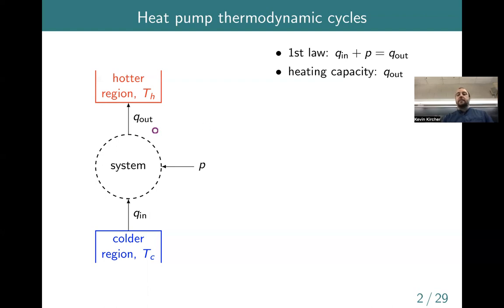Okay, we call Q out here the capacity of the heating system. So, if you're trying to figure out how big of a heat pump you need to keep a building cozy in the middle of winter, you'd figure out essentially what the demand for heat would be using stuff that we talked about in the last couple of lectures on buildings. So you'd maybe estimate the thermal resistance between the indoor air and the outdoor air, and then look at typical temperatures inside and outside, get an estimate of how many kilowatts thermal or how many BTUs per hour, if you're using English units, you might need. And then you'd choose a heat pump, basically the size of all the components, such that its capacity Q out is roughly equal to that number. We'll talk more about that in a minute. By the way, as always, if you have questions or comments, please let me know.